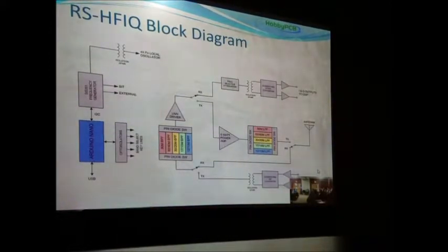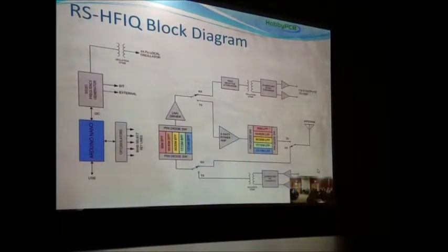And that's magnetically coupled into the quadrature down converter. So again, there's no electrical connection between where the I and Q outputs connect to the PC and the control system or the RF. It's all isolated to eliminate ground loops and switching noises.